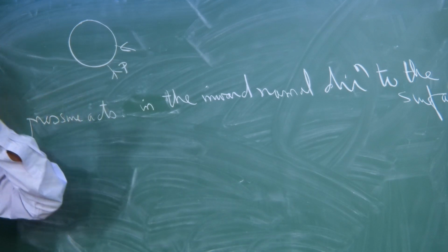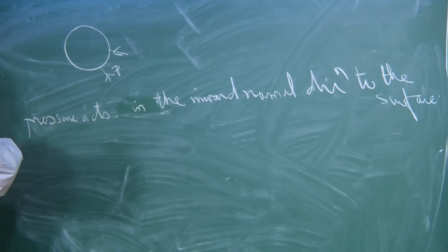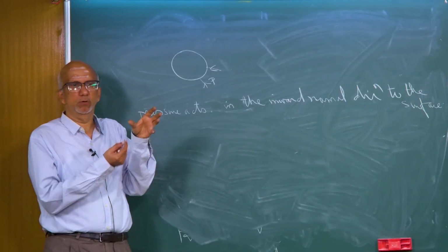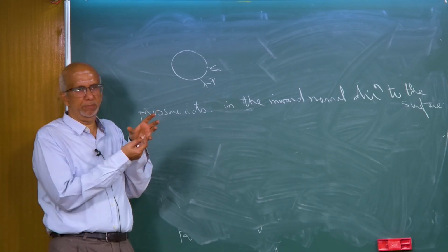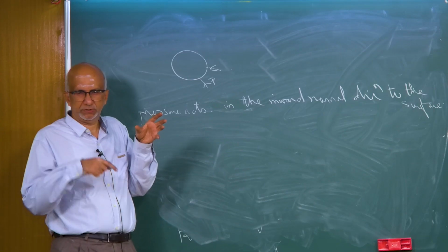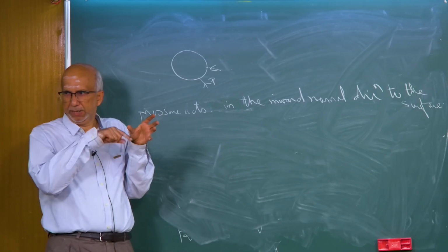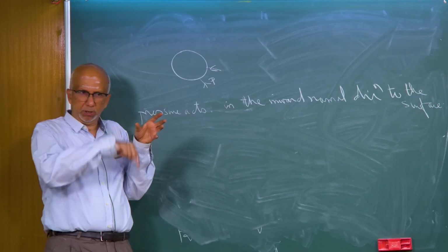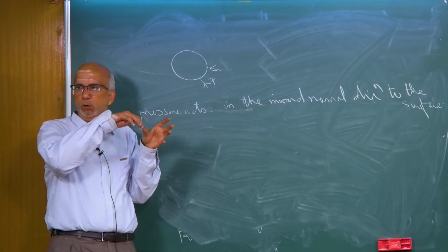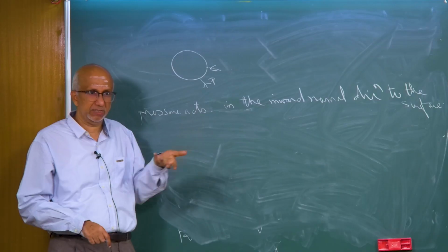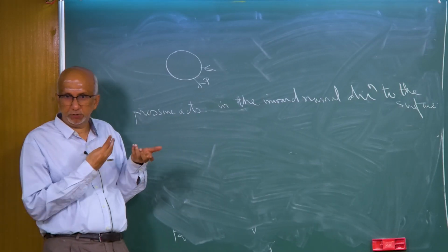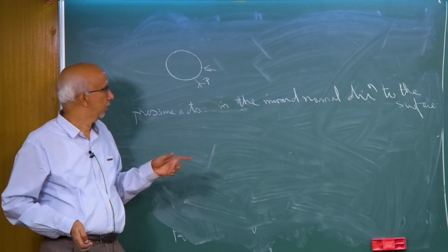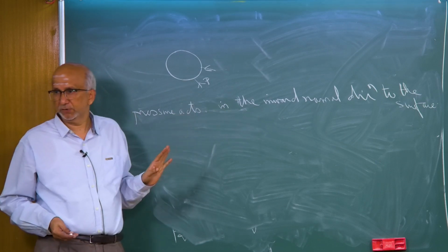I mean, if we have a sphere which is stationary, one way to understand this pressure is look at all the molecules which are going to come and bombard against the sphere surface. These molecules come, bombard and they will get reflected. So, as far as the fluid is concerned, the fluid molecules are experiencing a force in the outward normal direction. As far as the sphere surface is concerned, it is going to get the reaction force, which is in the direction of the inward normal. Okay. So, that is the reason I am saying pressure is in the direction of the inward normal.